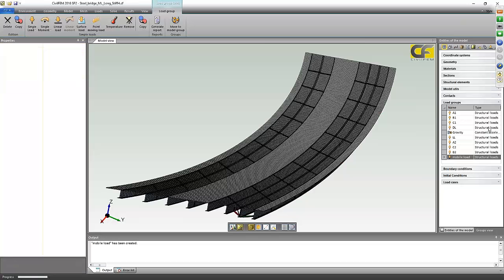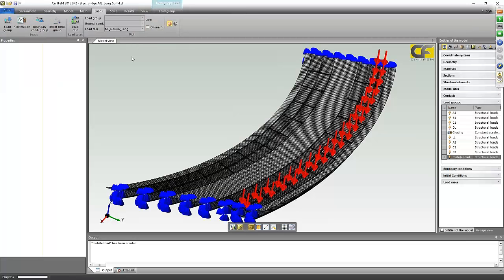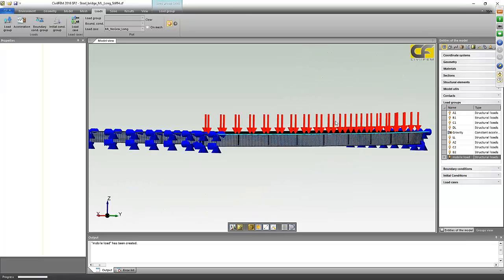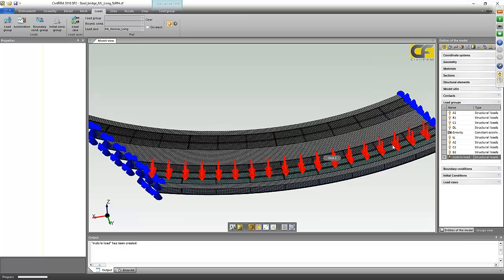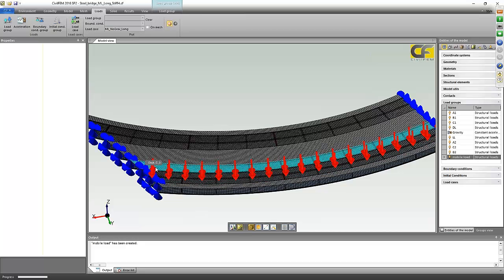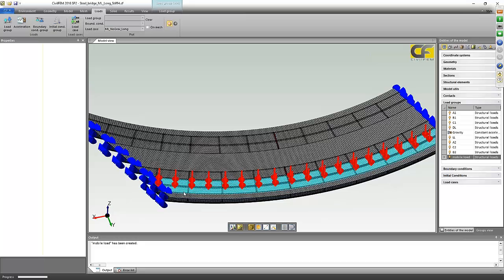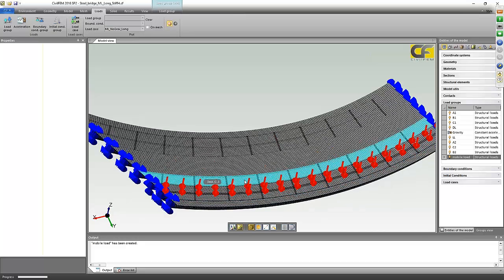I've done this previously, so here we have my loads, and I can plot them, clicking here, Loads, Load Case, this one. So here I'm plotting boundary conditions and the loads. Here you're seeing all loads together, but of course they are applied in 4 points, and then they advance in all these directions.